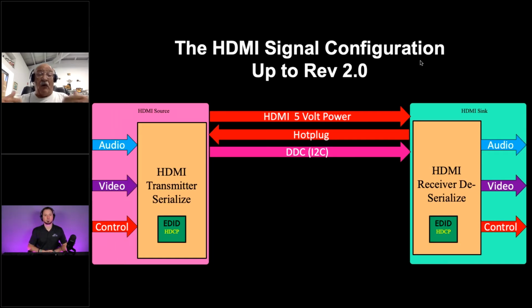So it will cause those rounding effects to occur. And then there's DC levels that also pertain to the 5-volt power. We'll talk about that later. So this I2C bus is very vulnerable, and unless we very much take care of it, it will raise havoc.